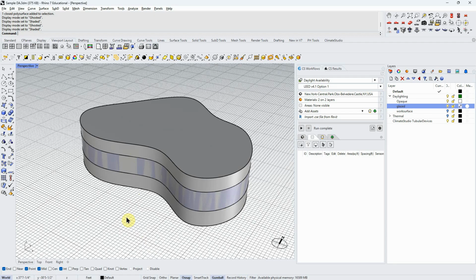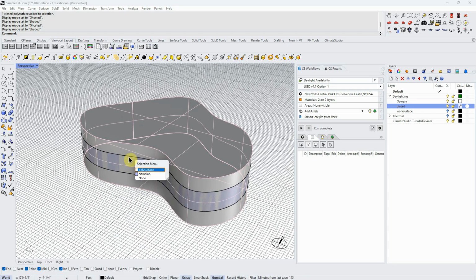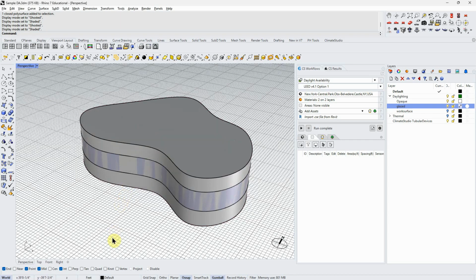They can be interior also, or we could actually punch the surface between these two lines out of the volume and apply the glazing to that hole. The reason I bring that up is because occasionally I have trouble getting this to work with the applied surfaces.